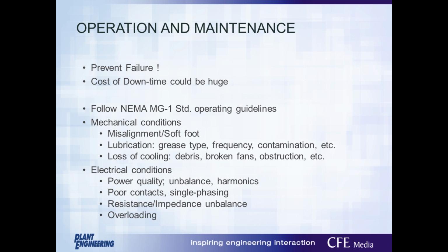First, we'll talk about the mechanical conditions listed. Even if a motor is aligned well at installation, various factors can lead to misalignment during operation. If the motor itself starts making some loud or strange noise, shut it off and verify the alignment. You can verify parallel alignment with a simple straight edge. To check for angular misalignment, you might need a telescoping gauge, which not everyone will have in their standard toolbox, but they can be ordered very quickly. They even come in packages covering many size ranges. What I have is a pack of 5 or so telescoping gauges that cover many different motor sizes.